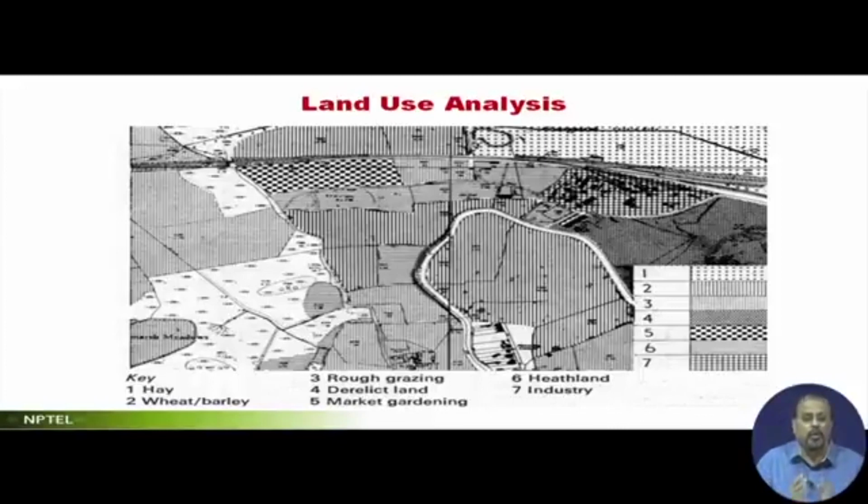This exercise should be done much before you start any other analysis, because if you find that the site which has been brought to you by a client, and which you are likely to develop for him, is subject to some kind of sub judice with respect to non-convertibility of that particular land to the other land use which you are thinking, in such a case all your exercise and your time spent, money spent, everything will be lost. So the point is this, you take care, check with the land use.